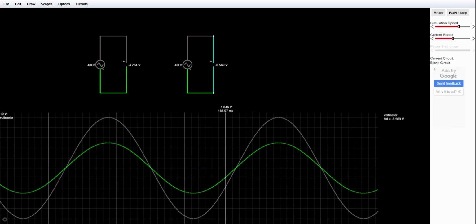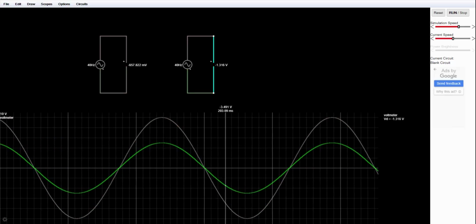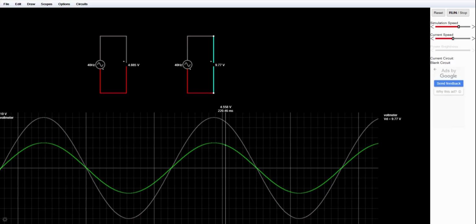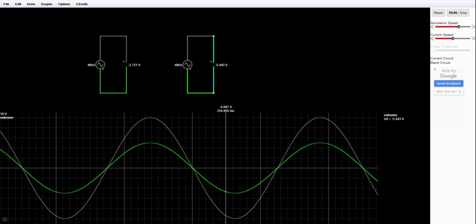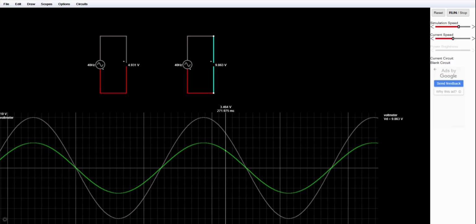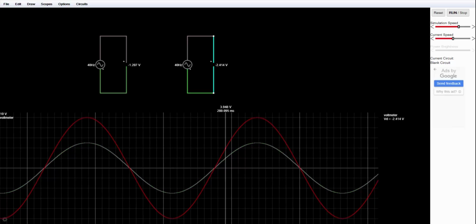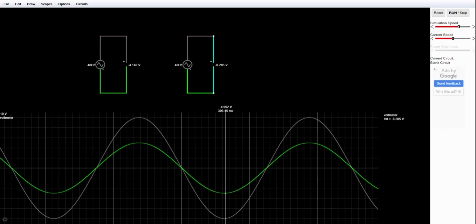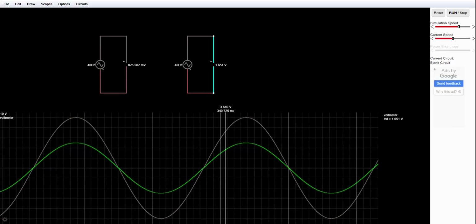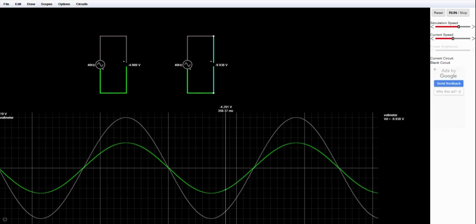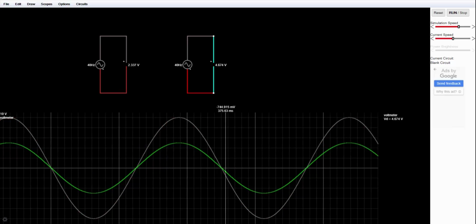Now, from the first video lecture on familiarization, where we talked about XY plot and Lissajous figure, you already know that the XY plot for such a case should be a straight line, right? There's no phase difference. XY plot should be a straight line having a slope which would not be 1 in this case. If the two signals had absolutely identical peak values, the slope would have been 1.